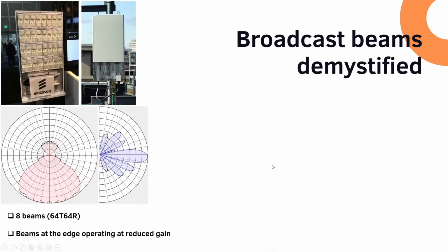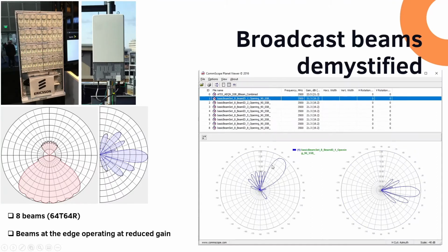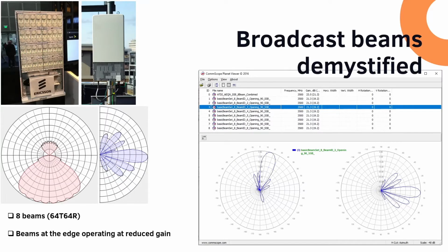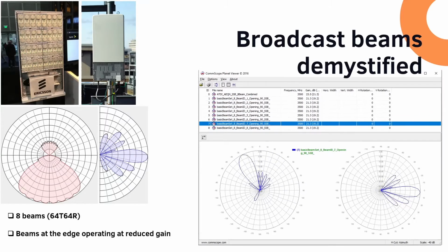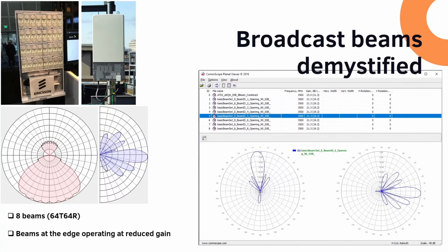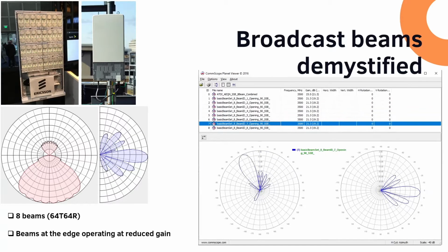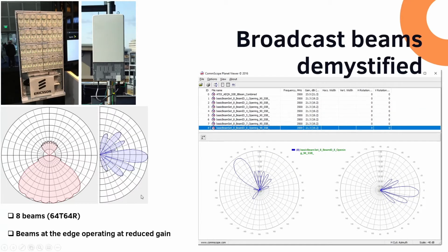I'm not going to talk too much about beamforming antennas, but this is how beamforming is working. You have individual beams running like this. The base station is alternating the beams. So what we do, instead of modeling as a single beam, we superimpose all these individual beams and we create a composite beam like that one you see on the left hand side. We combine these individual beams to produce something which is describing the worst case scenario.